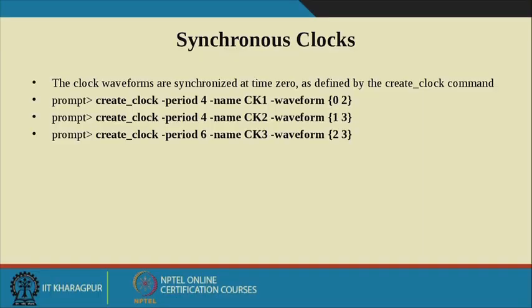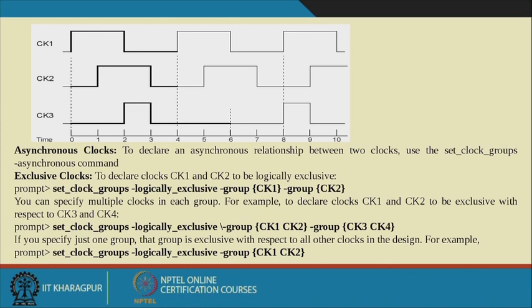And then exclusive clocks means we are having two clock sources, which are basically multiplexed. We have a multiplexed clock signal, like for reconfigurable applications or multi-mode applications. Whenever they are supporting different frequencies at different times, at that time we need different clock sources to the pin. So at that time you can use exclusive clocks. Synchronous clock means only one clock connected to each of the registers.